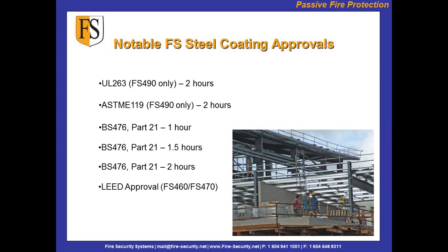For the 370, the 460, and the 470, they're all BS 476 Part 21, 1.5 hours and 2 hours, internal or external. And we have no VOC, LEED approval, and green build for 460 and 470. What you will find across the world is that's all that is ever required. But we're always keen to test more if required, especially if a customer requires us to do a test for them. We're more than happy to move forward that way as well.